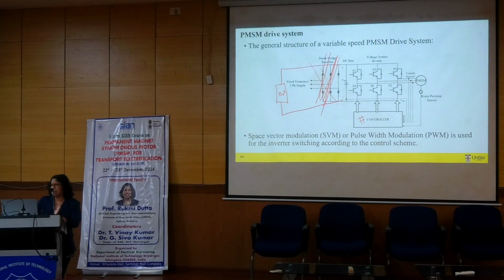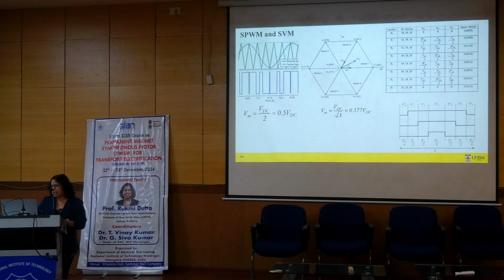Nowadays, nobody builds hardware PI controllers. If you use a PI controller, it all sits on the microprocessor only. And then just to remind ourselves, we could use PWM as sinusoidal PWM, or we could use SVM.